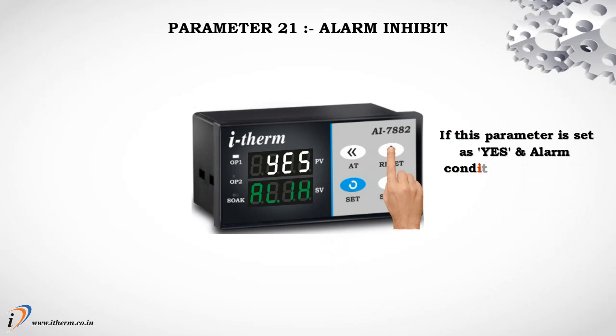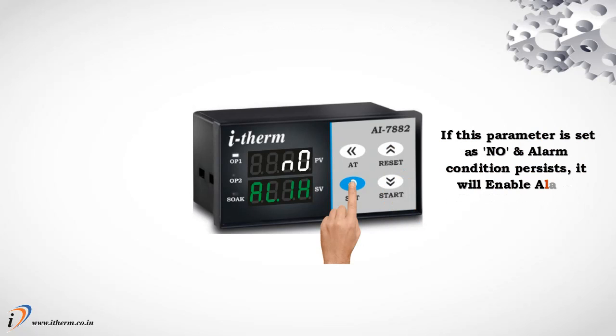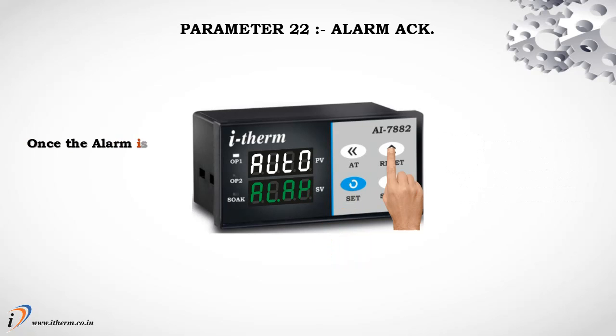Parameter 21, alarm inhibit. If this parameter is set as yes and alarm condition persists, it will disable alarm output at power on. If this parameter is set as no and alarm condition persists, it will enable alarm output at power up. Parameter 22, alarm acknowledged.